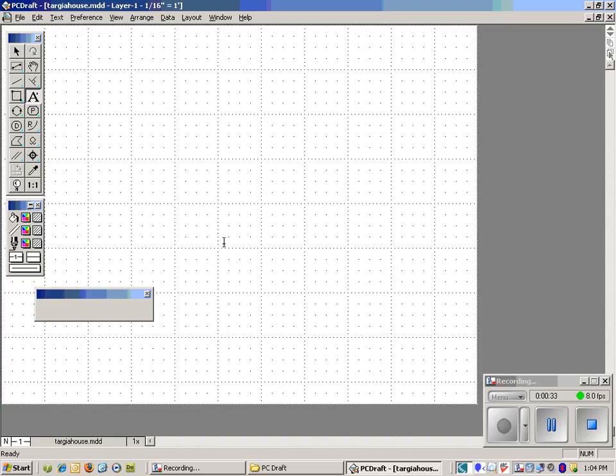If your house is 30 by 50, then you will begin with a rectangle that is 30 by 50. Okay, what that means is you're going to start with your square rectangle tool here, and you see these intersections on the grid. You want to start somewhere where there's an intersection on this grid, such as right here. Okay, and if I hold my mouse button down there and I begin to go over to the right, you'll notice in the show size palette that the number starts to increase at 2-foot intervals. If you remember, we're on a 2-foot scale right now. That's why every time it clicks over once, it moves 2 feet to the right.